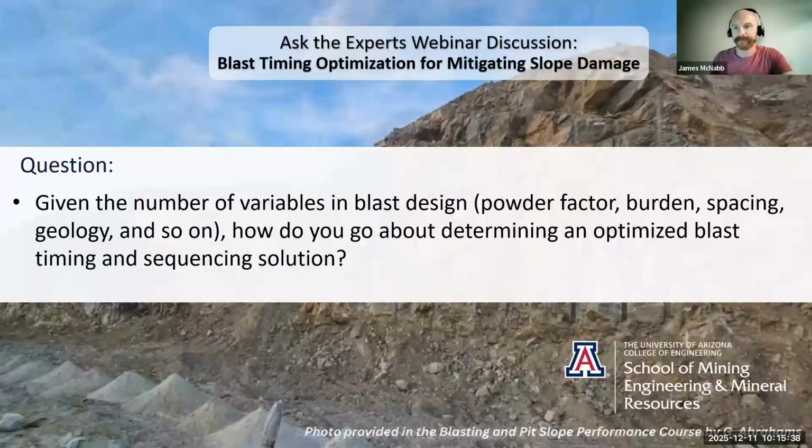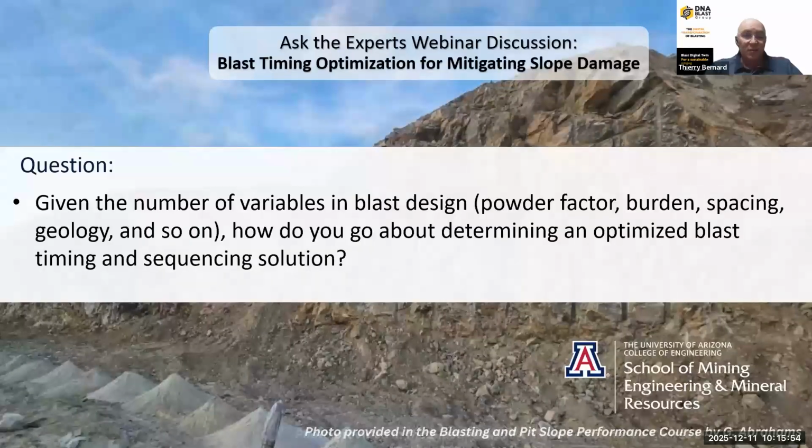Thierry? Yeah. When we're looking at the blast timing and the best delay to optimize the blast, I will say that the first thing, as was mentioned initially, is to first define the objectives. Are we looking to reduce the PPV or shift the frequency, or looking for good fragmentation or good movement or heave, or to control dilution?